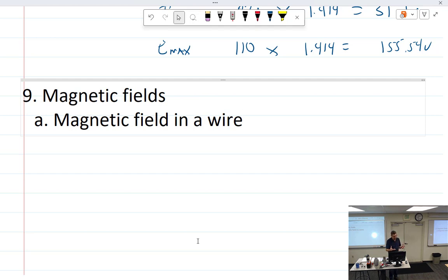And we talked about the fact that in a DC circuit, when we have any sort of coil next to another coil, if I power this one with a battery, a magnetic field will grow. That magnetic field grows, cuts across this one, and induces a voltage in it, but only once for a split second, because that's how long it took to grow.